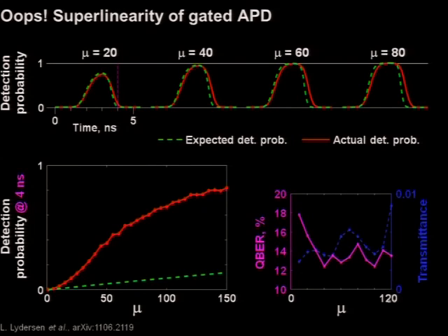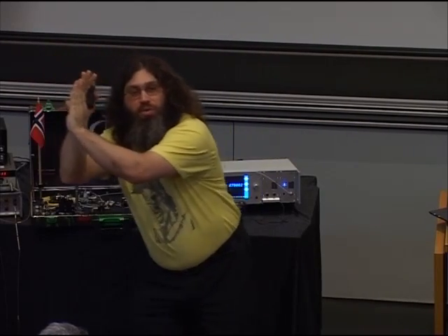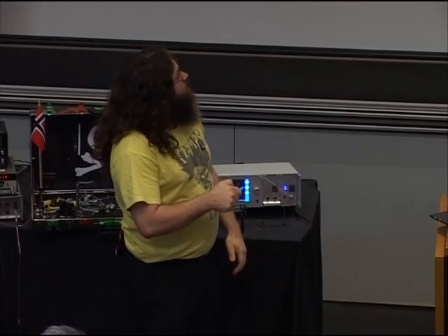And indeed, we have done tests on a gated detector in a Clavis2 commercial QKD system. We try to see what is the single photon sensitivity of the detector as we scan a narrow light pulse, a 200 picosecond light pulse, in time across the gate. We take this narrow pulse and scan the sensitivity across the gate.